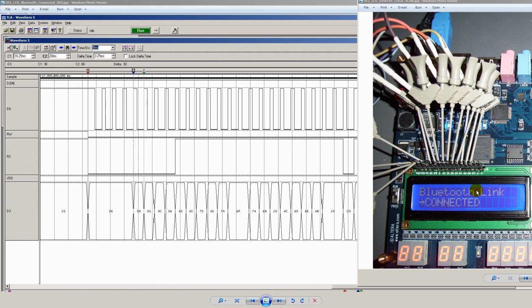Now you can notice here how in between Bluetooth and link we have a blank space. Well, that's the value 20. So 20 is essentially a blank space between words. So you have 20 here, which is the space between Bluetooth and link, and then we have the last 2 characters on the line after link, which dictates the end of the first line.